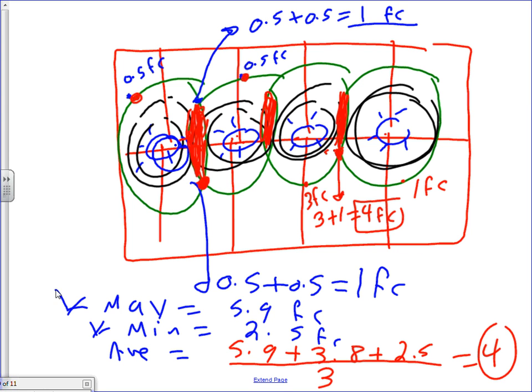We fully understand how lights add up from different fixtures. These are from 2 different fixtures. If you put 2 fixtures next to each other, the point in between them will get light from both of them and it will add up. If it gets 0.5 from this, 0.5 from that, it's going to be a value of 1. I need thumbs up for this one, guys. Here's another one. This fixture is giving me at this curve 3, this fixture at this curve 1. So where the curves cut each other, it gives me 3 plus 1, 4. So right here at this point is 4. That's what Visual is doing when you throw your fixture around. That's what Visual was doing for you. Can I have thumbs up, Chad? We understand that. Okay, so that's what I wanted to show you for these fixtures.